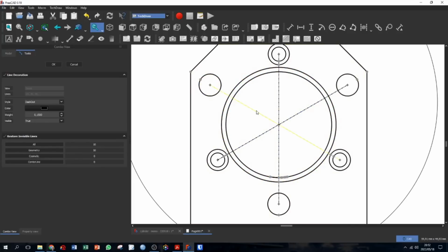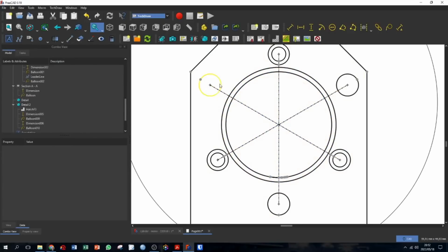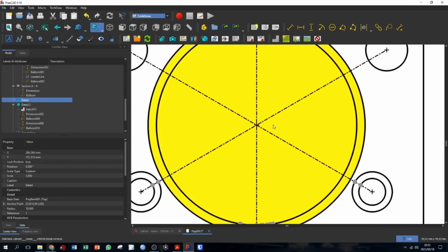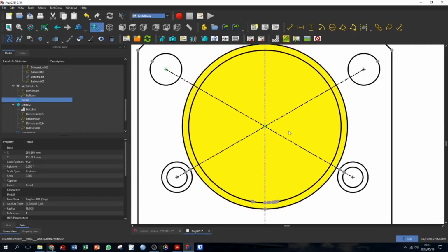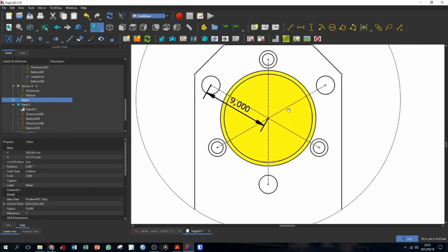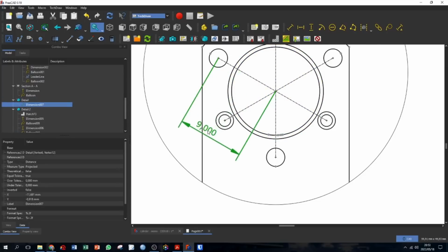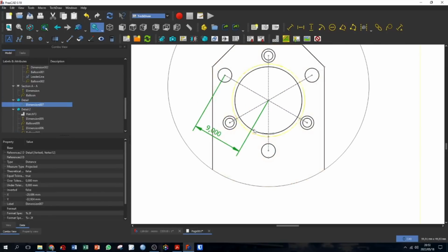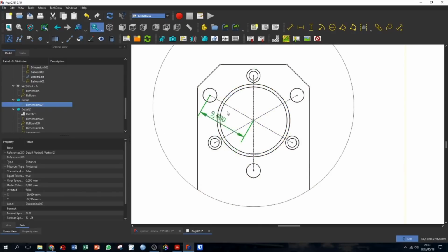Right, so what we'll do next is we need to indicate the distance, because as you can see, hopefully you can see it. So I want to indicate the, press and hold Control, select that point. This is a theoretical exact dimension. I think this can actually work if we put it somewhere there.